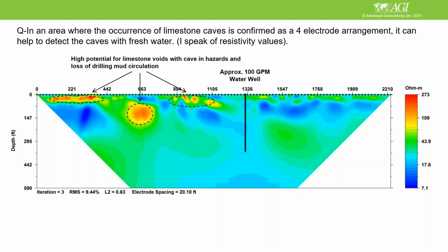So when you're doing geothermal studies, when you do vertical electrical sounding or electrical imaging, you can see where the hot water is, and that hot water lowers the resistivity values, so the area becomes a little more conductive.